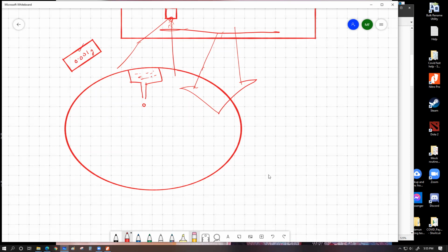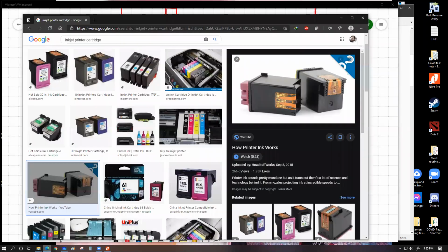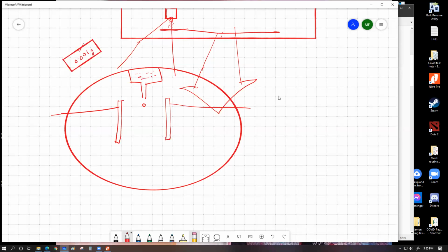As the droplet comes out, we have two metal plates placed beside it. We can charge these metal plates from the circuit of the printer, as we want. We can apply any type of voltage. You can apply positive and negative voltage, or negative and positive voltage. You can keep them neutral. And how much voltage do you want to apply? We can choose it by the circuitry. That's basically what is delivered from these points. Each of these connection points practically controls the exact voltage applied to the two metal plates placed on the two sides of one of the nozzles.